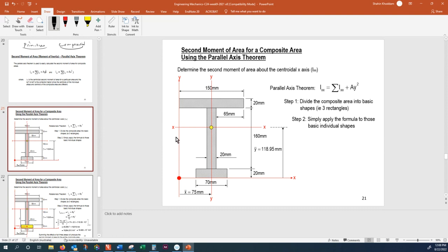Yes, thank you, Ivan. There are three primitive shapes. For every primitive shape, you find their corresponding I value from the table, from the formula sheet. And then you have to do a cooking. That cooking involves using the table formula sheet, using the parallel axis theorem, and also the compound principle which I mentioned to you.